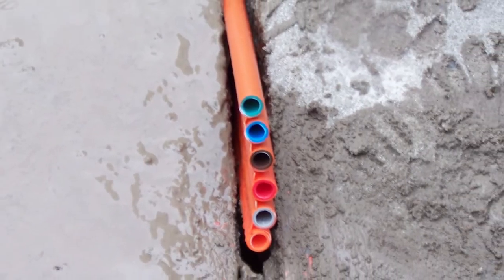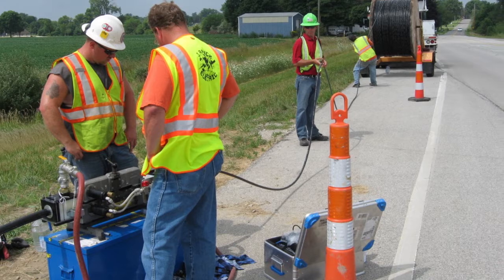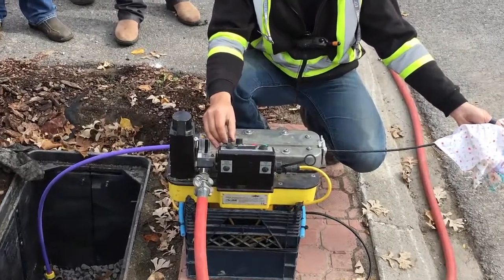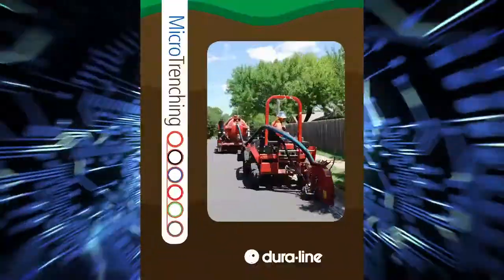Once the conduit pathway has been placed and the restoration process is complete, the fiber can be installed into the pathway. Typically, the fiber is air-jetted or pushed short distances into the pathway. For more detailed installation information on microtrenching, please request more information from Duraline.